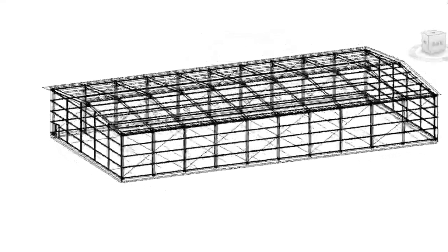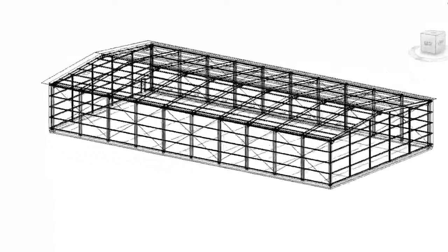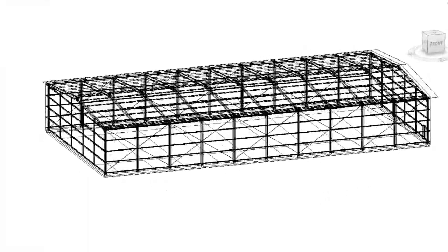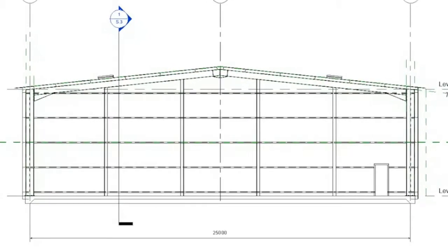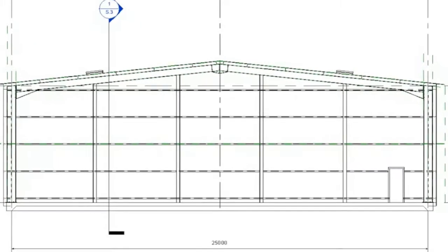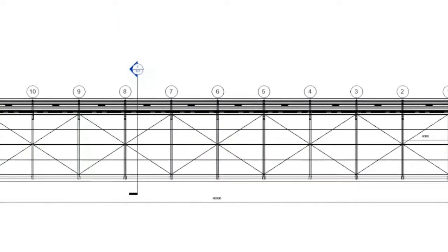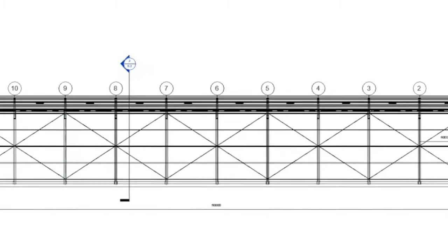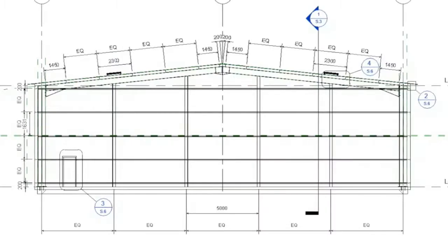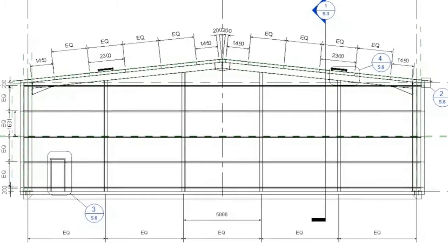With the advice of the CIVL201 tutors and Professor Tim McCarthy, the spacing of the portal frames should be limited to between 5 and 6 metres. The spacing of the portal frames has an overall influence on the design of member sizes and the connections. These include columns, rafters, purlins, cleats, girts and bracing. A larger spacing between frames results in the increased sizing of the required members.